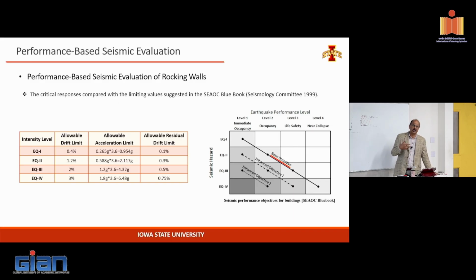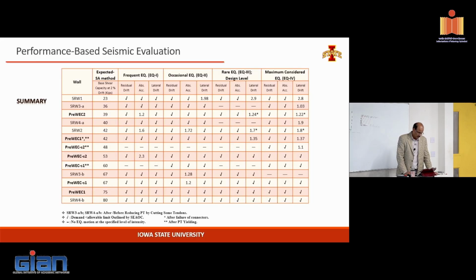So we felt like with the jointed system and unbonded post-tensioning, you can actually promote this idea that you can design these more resilient structures with the potential for being functional after the earthquakes. So we set some criteria as to what the structure should do in order for this to be functional. So, for example, for each of the earthquake levels, we had residual drift, because you don't want the structure to lean after the earthquake. So the residual drift is a criterion.